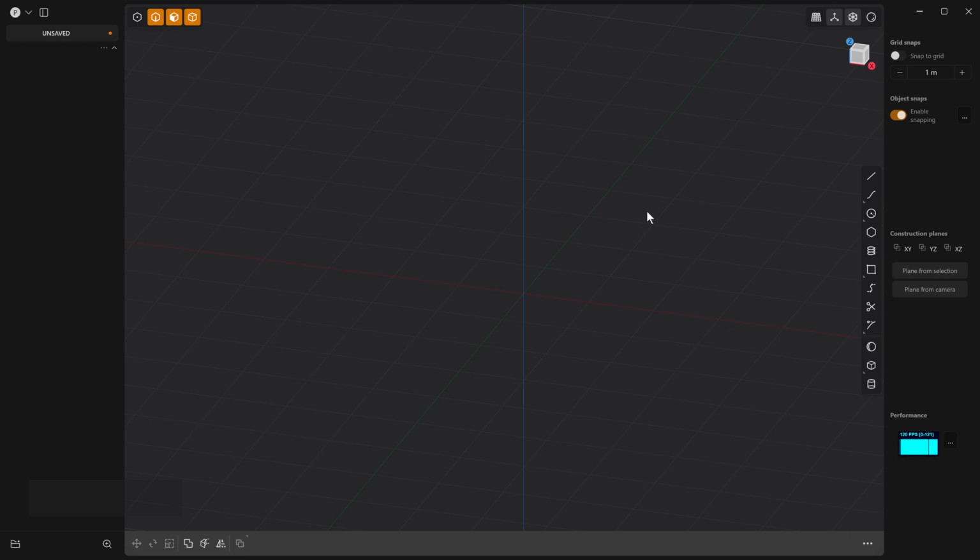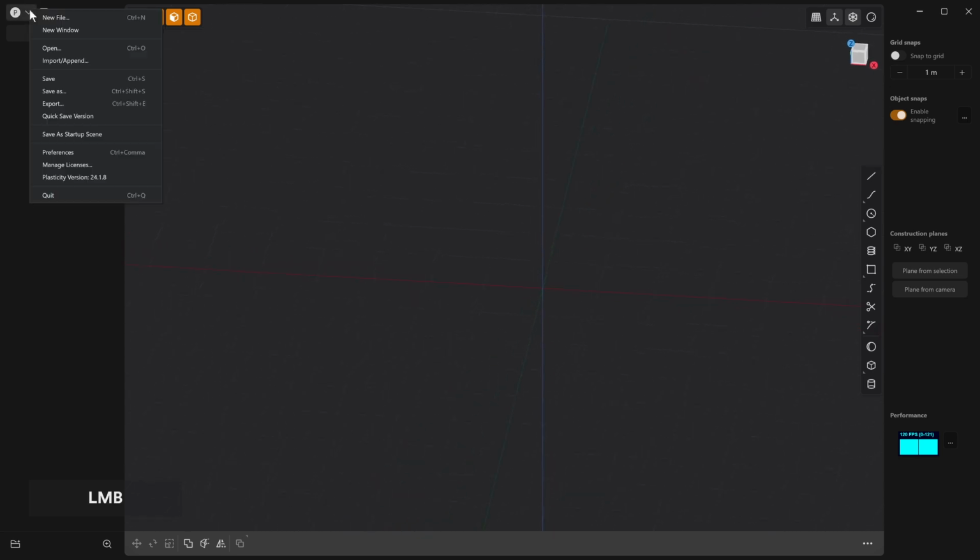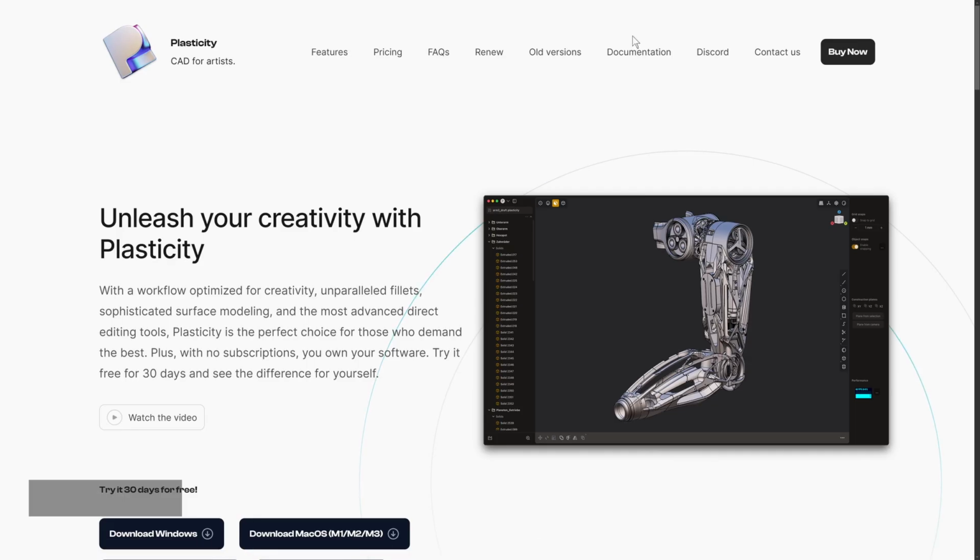So if you really want to get into the meat of Blender and coloring your icon, feel free to skip ahead, but I'm just going to shoot past this. So to skim past this, I want to kind of explain some basics. So first and foremost, in order for me to bring an SVG into Plasticity, I need to create a STEP file. I can't just bring in an SVG, a scalable vector graphic, into here.